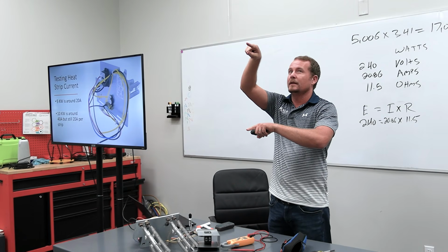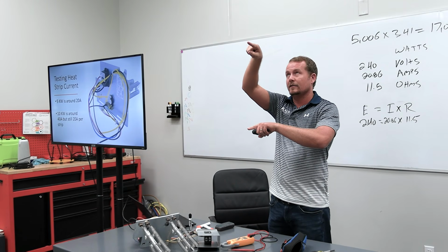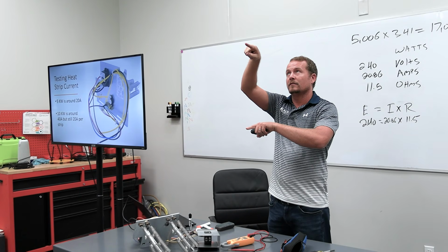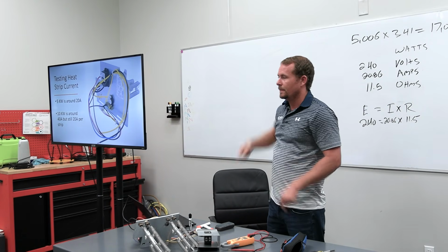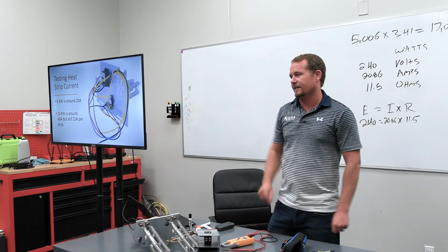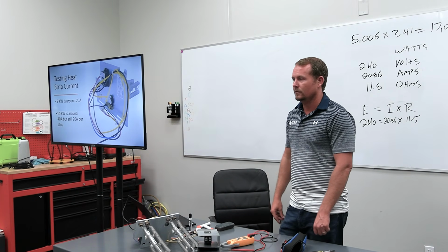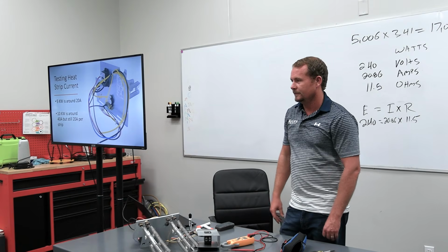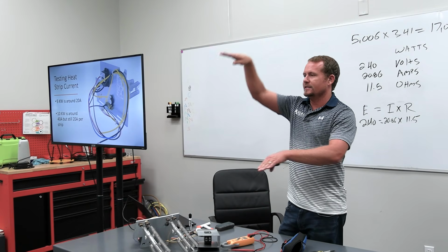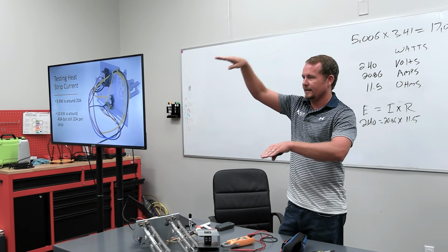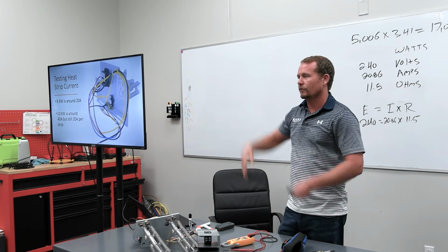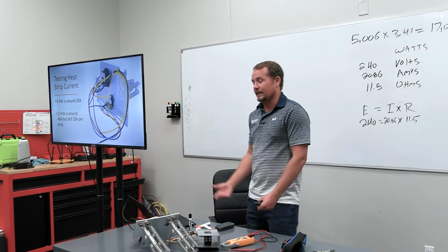What would it be if it's thirds? It'd be 120 degrees out of phase, from here to here. So because the phases aren't lined up, now you have a lower voltage between phases. So that's why you have 208.